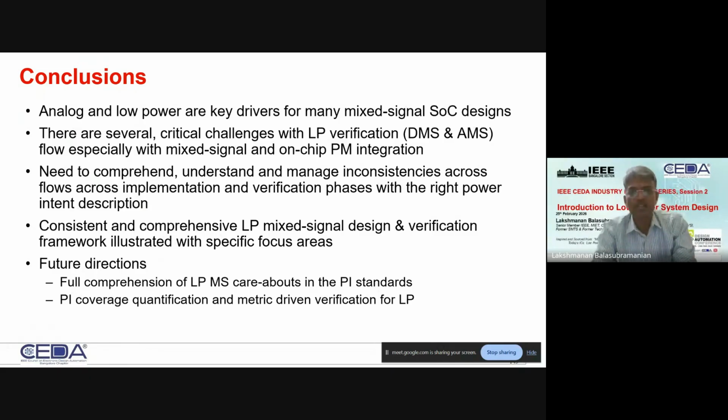There are several critical challenges for low power integration and verification, especially with mixed signal integration. There is a need to comprehend, understand and manage inconsistencies across flows. The flows have to be consistent across implementation, verification, custom and semi-custom flows, standard cell building, and then at RTL level and gate level across entirely different phases. And they have to be consistent, and a comprehensive low power mixed signal design and verification framework is illustrated as an example here. And there are some future directions.